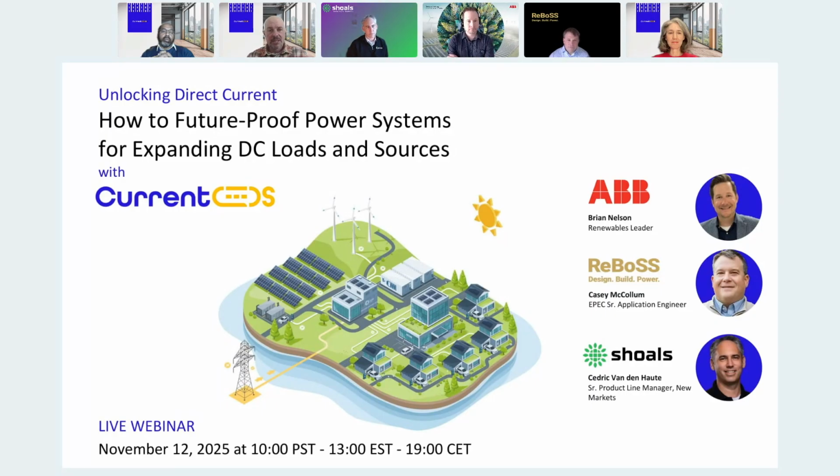Awesome. Brian, you want to take that one next? Yeah, Casey hit the nail on the head there. From ABB's perspective, of course, IEC 60947-2 is obviously a standard that we're leveraging today to bring to market one of the first solid state circuit breakers that is, I think, going to be instrumental in the future of direct current systems and microgrids. As Casey mentioned, there's this arc flash potential that needs to be managed, and it needs to be managed in a different way.